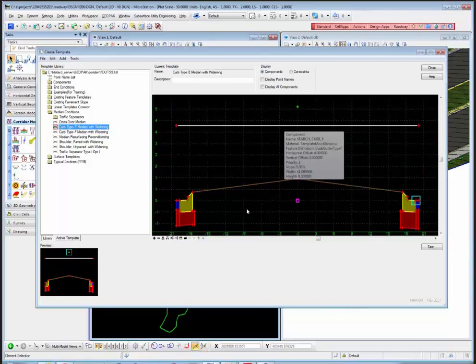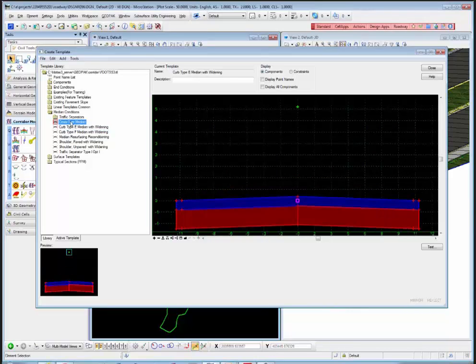Of course, they all work this way, so that depending upon which side you're targeting for that varying taper line, it will automatically stretch to it. And they all have trigger lines, and they all are basically component sets that you can drop in on a template. And then there's a crossover median, which is a standard median. Now the crossover median now has a couple of extra control points here. This is for basically controlling the crowning across an intersection instead of trying to be crowned about the middle. We know that when you've got a traffic separator far to the left on one side of the intersection and far to the right on the other side of the intersection, it can't crown down the middle because it has to transition that pavement slope. So we have these extra points in here, and these can be targeted on either horizontal features or point controls or something like that.